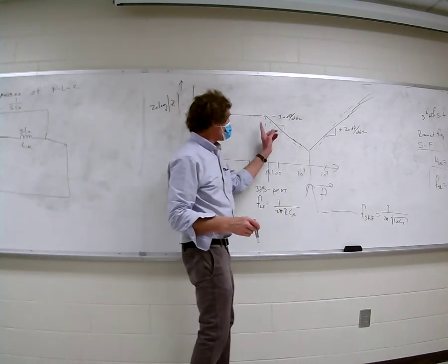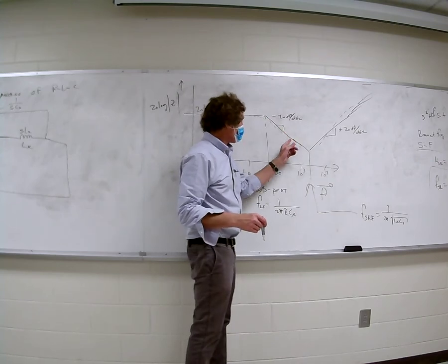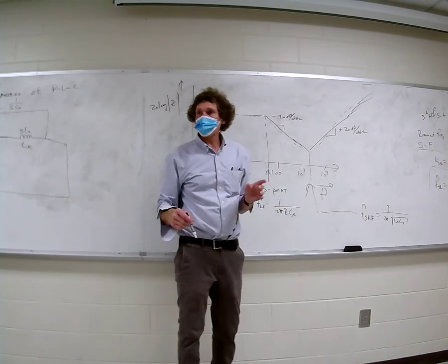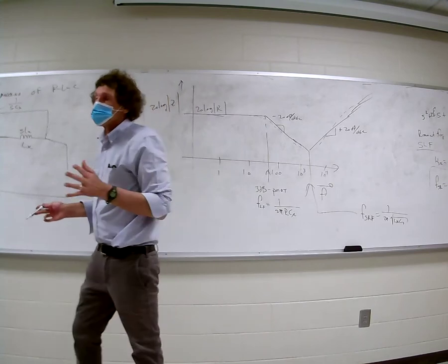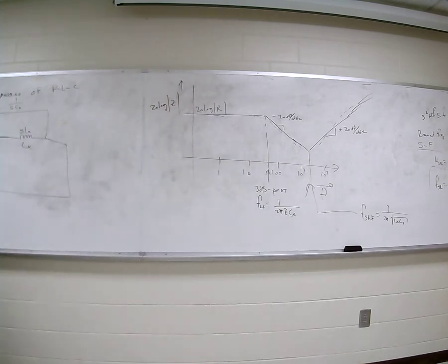I get something that comes down, then goes up, slightly different. This is the way it'll be generally. That's almost universally accepted for a common resistor with a given internal inductance and lead inductance and a self-capacitance. There are some exceptions, but very few.